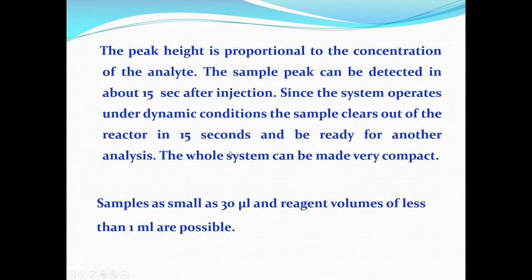The peak height, in this case, is proportional to the concentration of the analyte. The sample peak can be detected in about 15 seconds after the injection. This much time delay you can always give whenever you are operating a machine in flow injection mode.